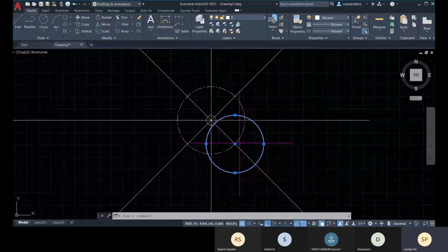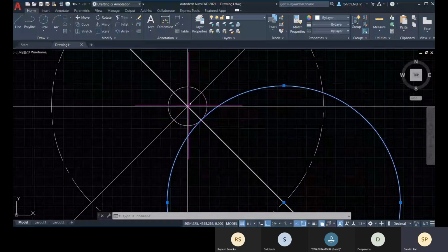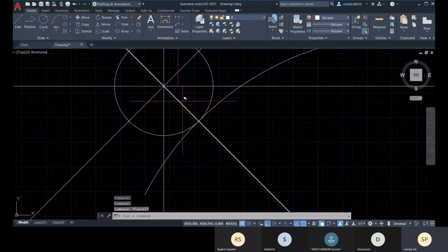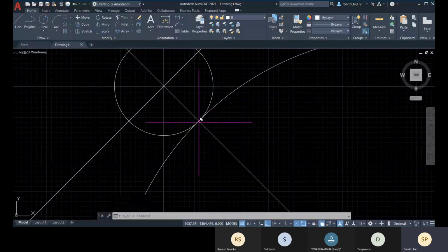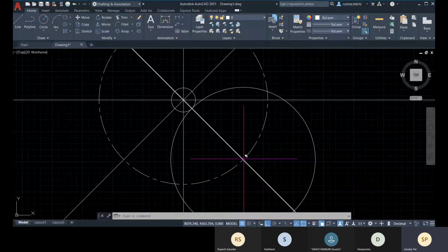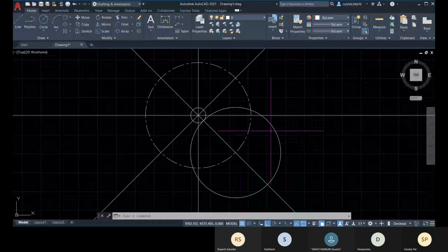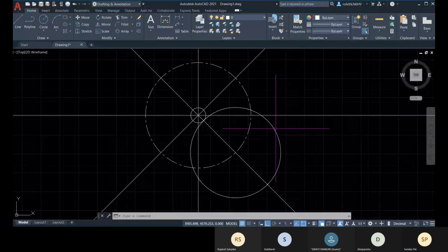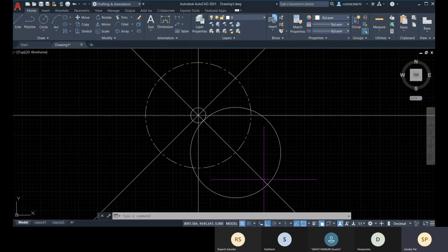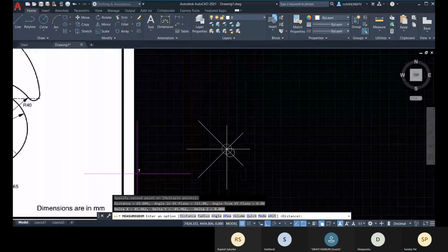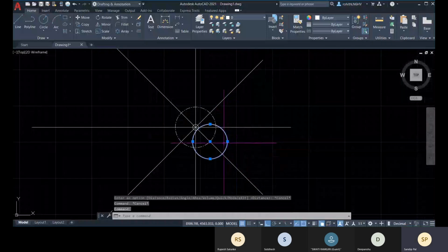So how much is the distance? Here you can see that it is properly tangent with this radius 5. So from this center to this point is 5, as because this is radius 5, right? And here you have see that this is your 35, right? So from this center you have this 35 totally, and this is what? This is radius 30 circle. So from this you have 30. So from this center to this end, you have 65 distance, right? 65 distance, and which is right now tangent with this circle, right?